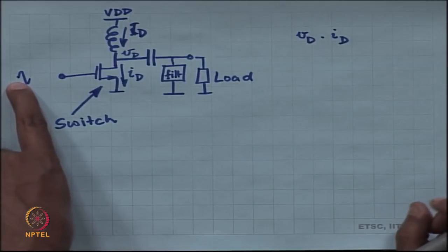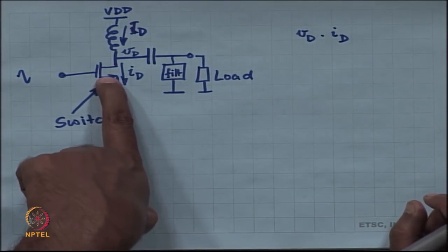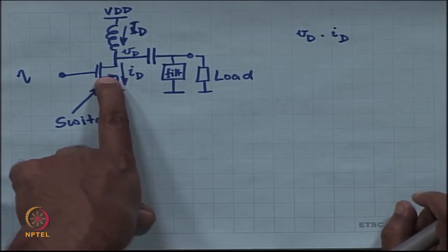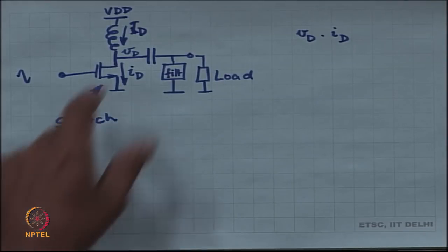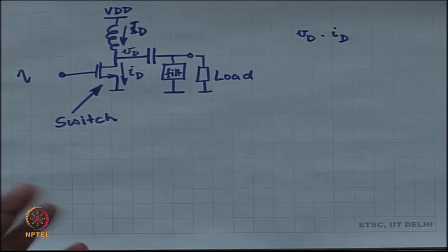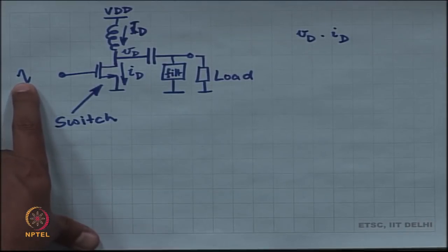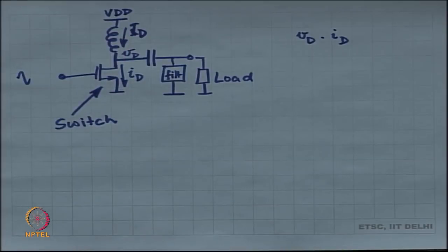What you are going to do is make sure that the signal is enough to switch the device either on or off, and the MOSFET is not going to behave like an amplifier at all. The input amplitude is so large, so strong, that the MOSFET is going to work like a switch.